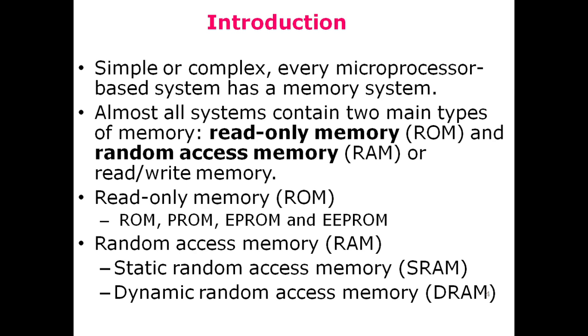Later on, a programmable version of the read-only memory was also introduced, called programmable ROM or PROM. This type of memory is not very commonly used. In programmable read-only memory, the data may be written later on using a ROM programmer. And then there is EPROM, erasable programmable read-only memory. It's the kind of memory that can not only be read but can also be written to later on in the field.